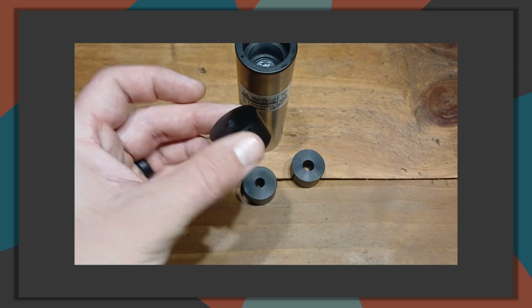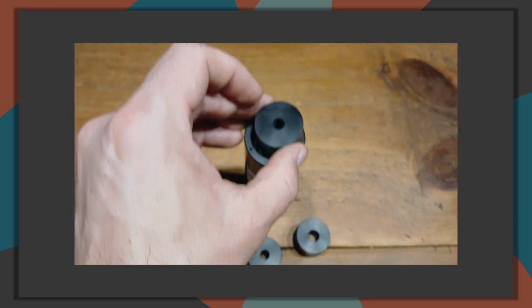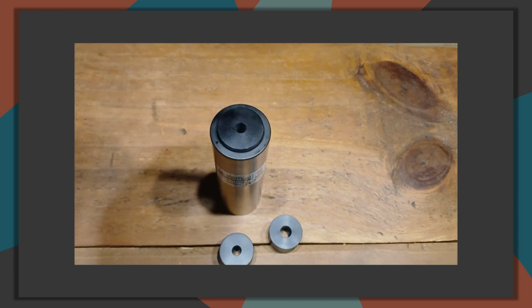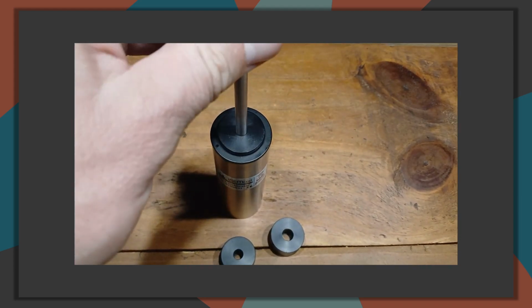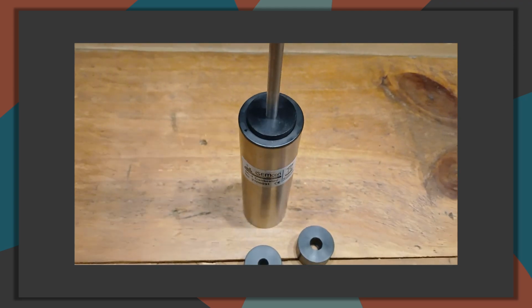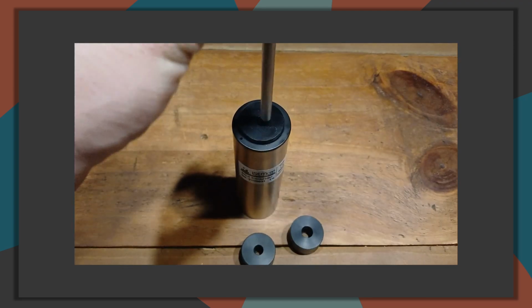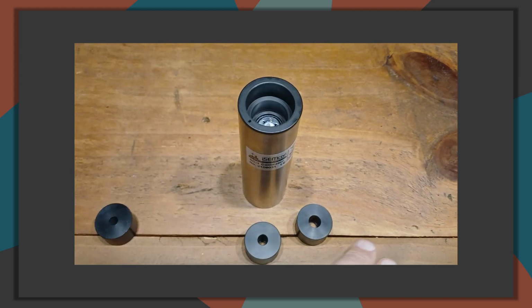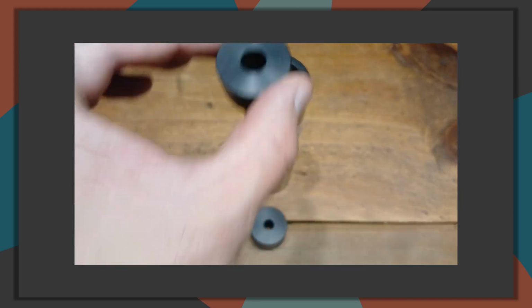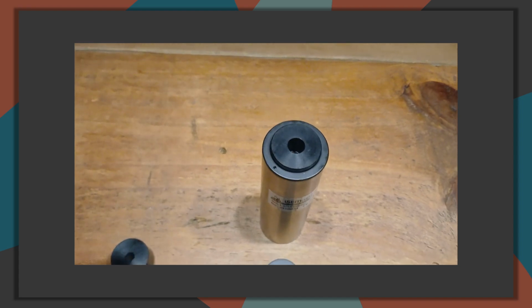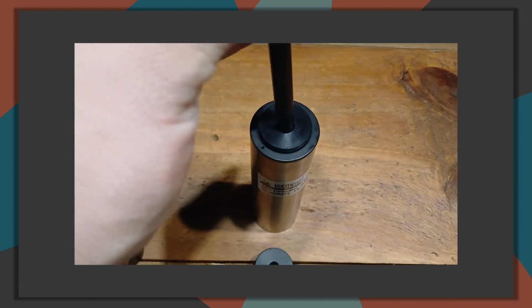This one generates a 1000 Hz tone and can be set to either do so at 94 dB or 110 dB. This one comes with inserts to match the measurement microphone's outer diameter so that it fits nice and snug in the space where the little loudspeaker is. For interest's sake, 94 dB SPL refers to 1 Pascal of sound pressure.